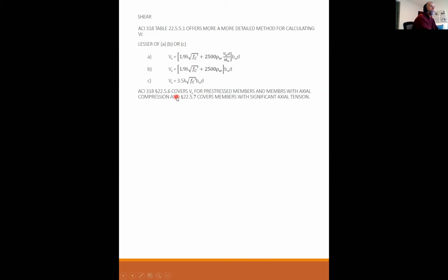ACI 22.5.6 covers V sub C for pre-stressed members and members with axial compression. We are going to touch on this when we get to columns, axial compression. And 22.5.7 covers members with a significant axial tension, which we're not really going to cover in this course. For the scope of this class, we're going to stick with the simplified equation, 2 square root f prime c. Any questions so far?